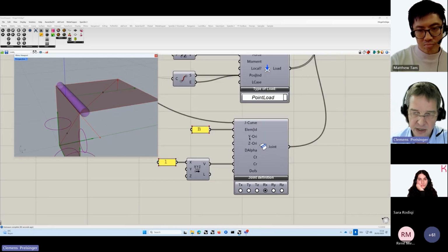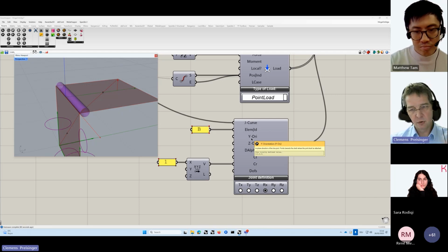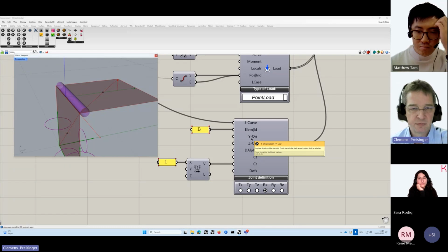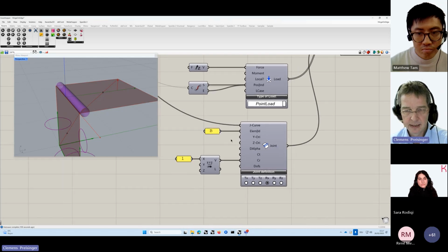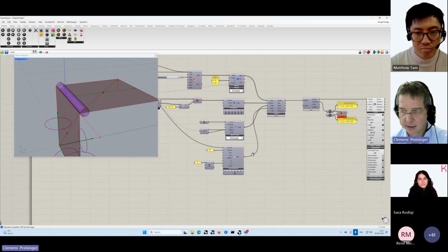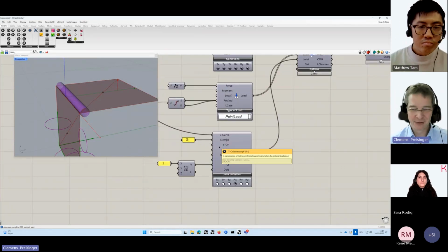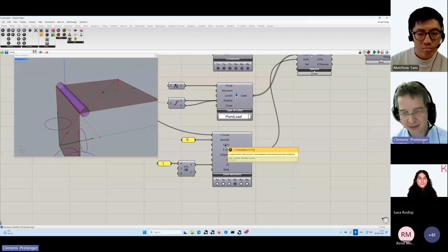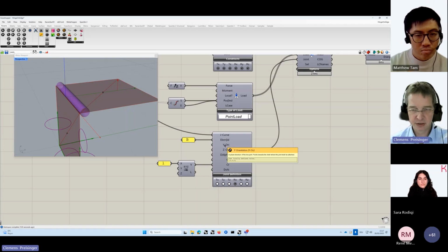And the option of specifying directions here is still available, because in complicated cases where there are more than two surfaces joining each other, it's still necessary to specify on which of these three or more surfaces the joint shall lie. So in that case, you still need to supply directions here. And yeah, that's basically it. In very, very complex situations where the orientation of the joint continuously changes, you can supply here the direction at the beginning of the line joint, and then it will automatically adapt to the changing position of the surface.